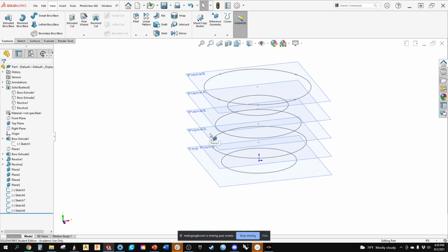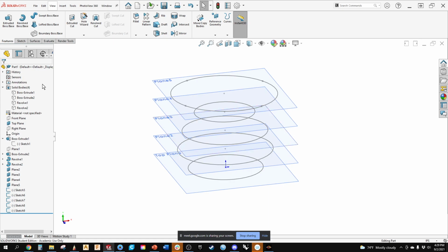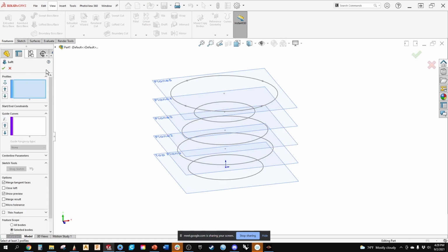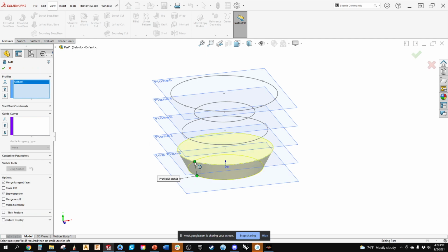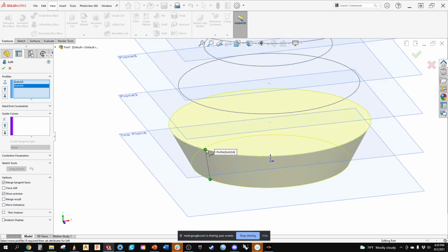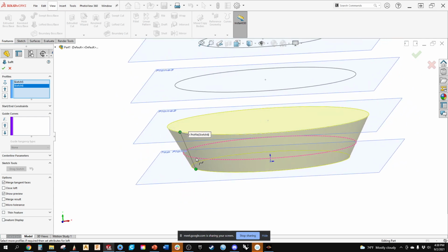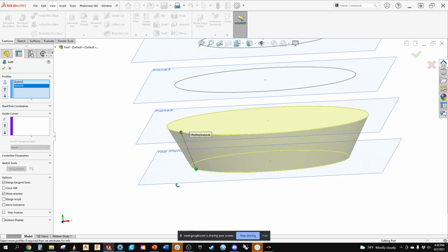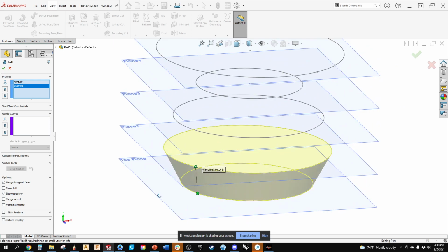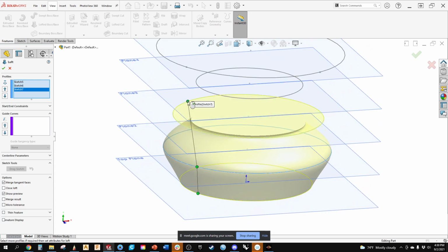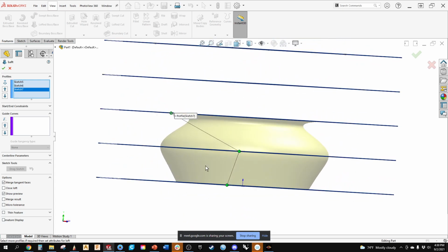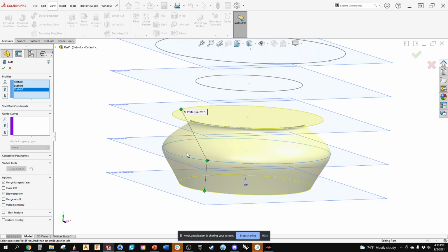one of the things that is very tricky that happens a lot is when I do a lofted surface and I select here and then I select here. See how there's this green dot? That's trying to communicate where the start and end is so that they're lining up. If I go too far away, so if I try to loft up to here and I select there, see how it goes all the way to the other side? It's trying to twist it as it goes.